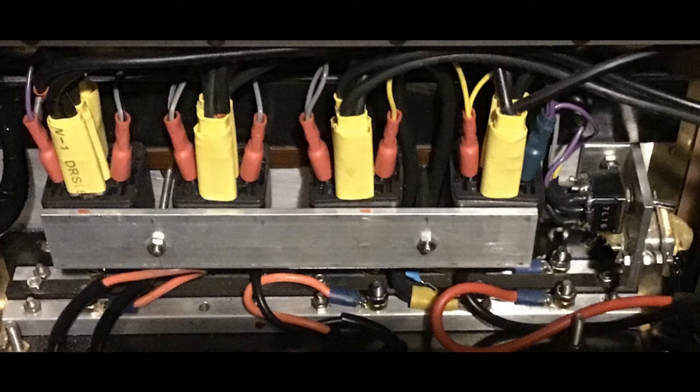Since the Uni 8 is unidirectional, I used automotive relays to provide reverse. These are arranged to operate in parallel for 12 volts or series parallel for 24 volts, as selected by a switch on the right of them. They are mounted above the tender motor bus bars. The train reversing switch is on the hand controller and should only be operated at rest. It's a locking type to avoid inadvertent operation.